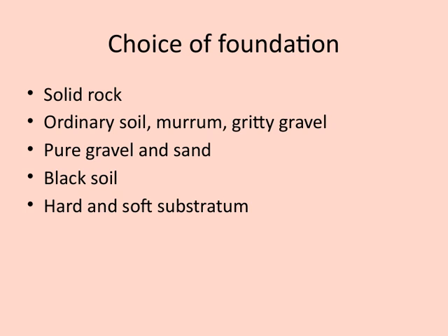We also need to consider the nature of the substratum, whether it's hard or soft. Hard substrata are preferable because they provide a firm foundation, whereas soft substrata might demand additional reinforcement or special foundation techniques to prevent settling or shifting. Understanding these different types helps us decide on the most appropriate foundation for safety, durability, and cost-effectiveness, tying back to the overall goal of constructing resilient structures.